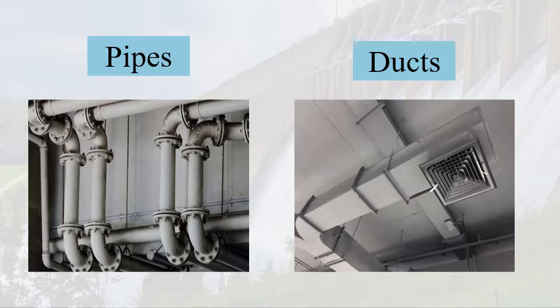You have probably noticed that most fluids, especially liquids, are transported in circular pipes. This is because pipes with a circular cross-section can withstand large pressure differences between the inside and the outside without undergoing significant distortion. Non-circular pipes are usually used in applications such as the heating and cooling systems of buildings, where the pressure difference is relatively small. The manufacturing and installation costs are lower and the available space is limited for ductwork.